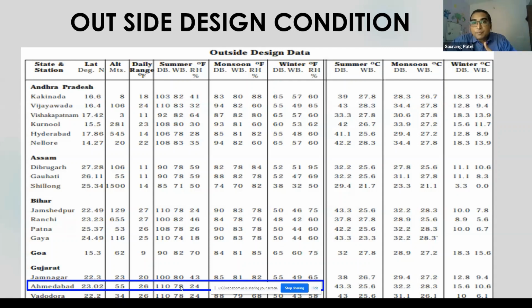Now if you have different applications and would like to go month wise, we have data available month wise also. Maybe you have specific applications which are not round the year, and you would like to design for a specific month. This one is for yearly applications. We have weather data books which give the same. So in the normal case, when doing cooling load calculation, we take the peak summer temperature from the data books. If you are doing heating load, we will use the winter months.